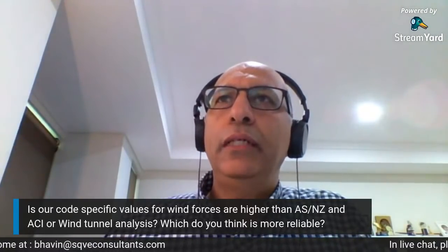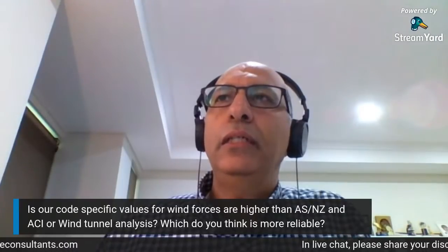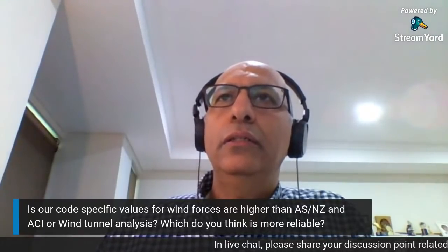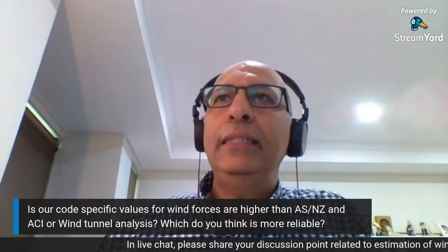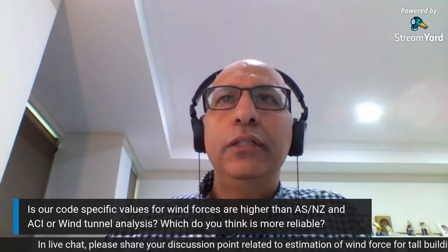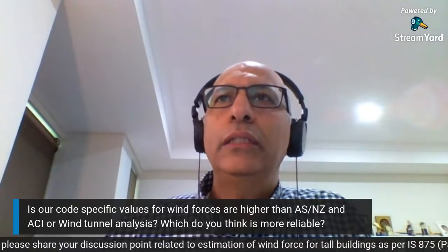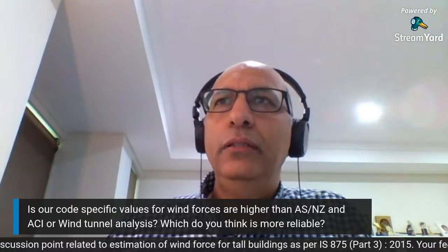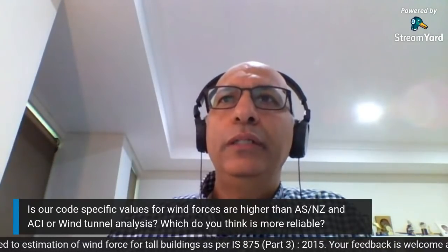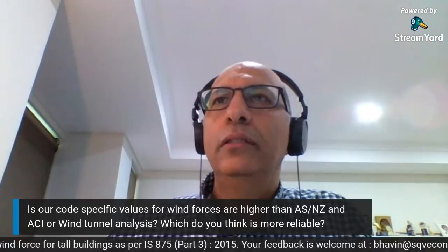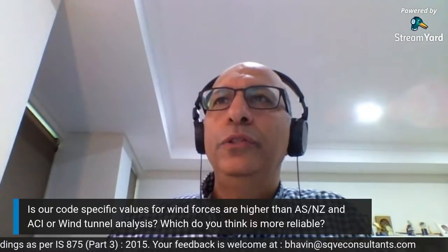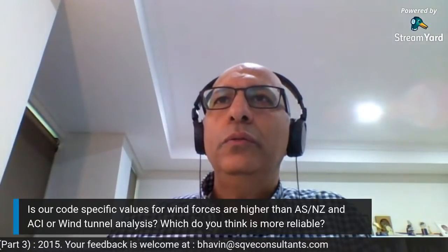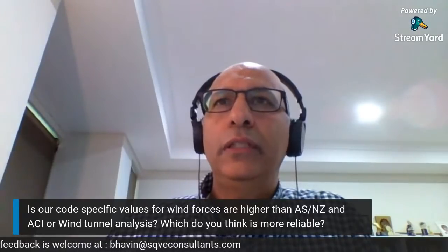So I'll just read it out: with height greater than 150 meters, or with complexity in plan or elevation geometry, or sited in complex topography, with group effect or interference effect, existing or future potential, or with a natural period greater than 5 seconds.